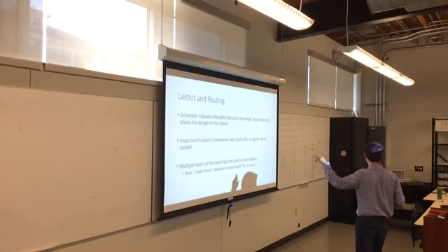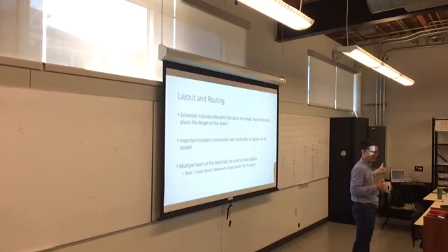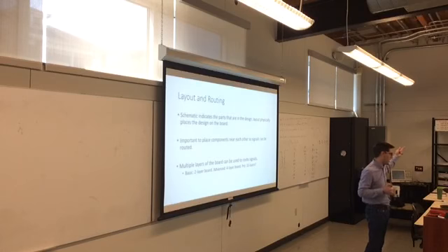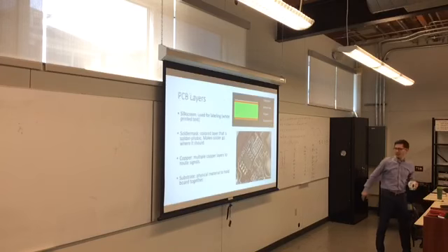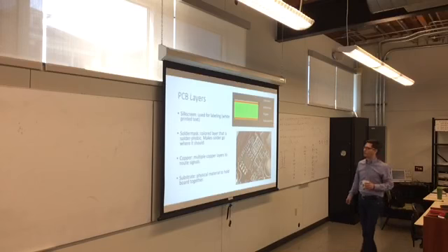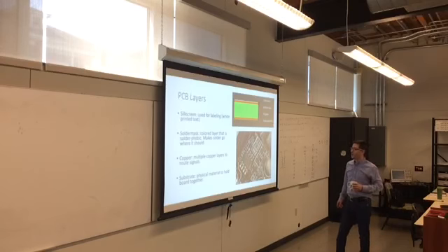If you've got 4 layers, well then now you've got yourself a whole ground layer, you've got yourself a whole power layer, and now you've got 2 layers where you can put random signals all through it. 10 layers, and you're really doing something crazy, because if you really need a 10-layer board, then you've got a lot of stuff going on.